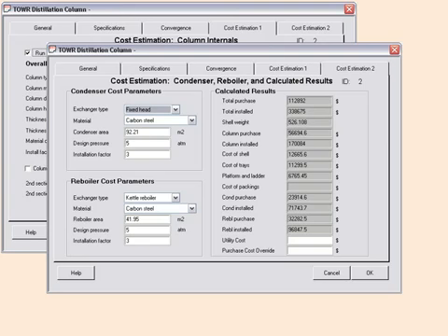We then run the column, and then by double clicking on it and coming back to the same menu, we see that the total installed cost of our distillation tower is $338,675. Of that, the installed cost of the reboiler is just under $97,000. The cost of the condenser is just under $72,000. And so these are the various elements that make up our distillation column and give us the value of what it would cost.